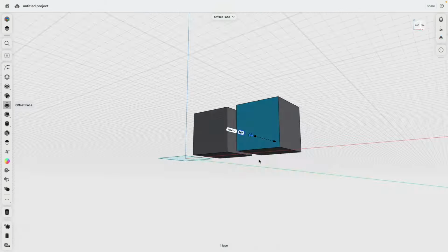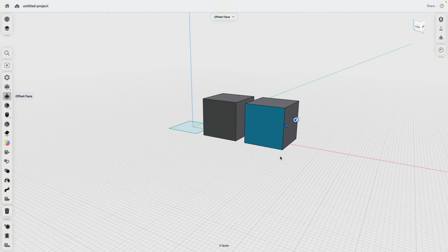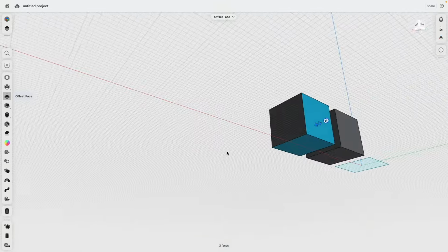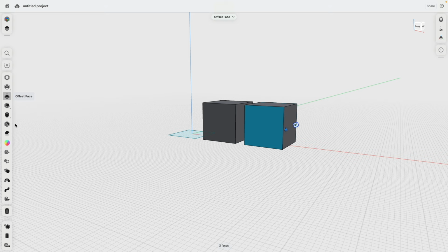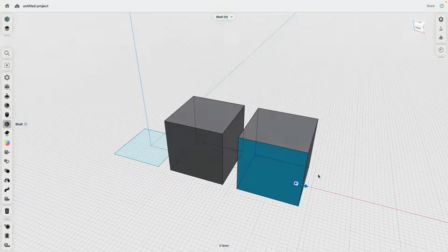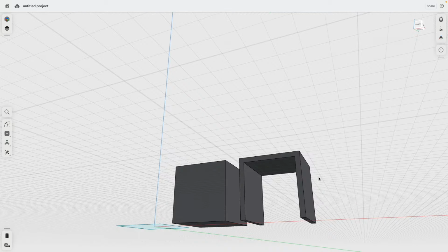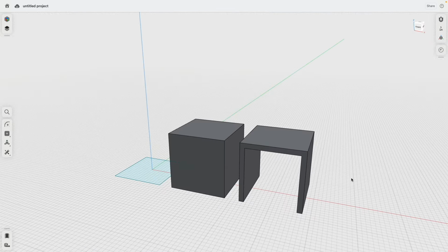Now, I want to do a very quick study how this could look when I have a board top and two sides. So I select, as you can see, the front, bottom, and back surface, and then select the shell command. We can slide this to play with the look. Let's say 1 inch and a quarter. Beautiful. Okay.